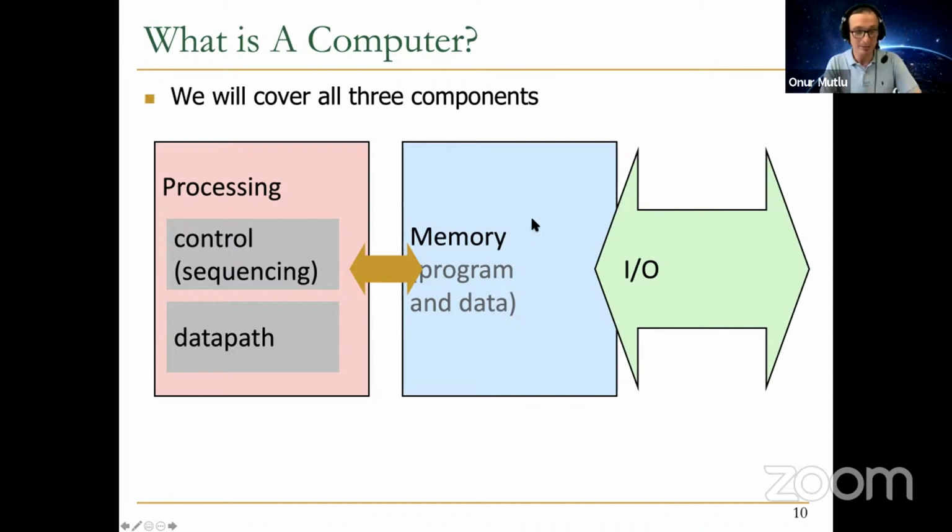But memory, I should say, consists of a lot of interconnects, and you will see that as well. You have seen it earlier, and I'm going to show a picture that you have seen earlier as well. To access the memory cells, you need to go through wires, lots of wires. And a lot of the memory latency is dominated by the interconnect latency. So we try to reduce that latency by reducing the length of the interconnects as much as possible.